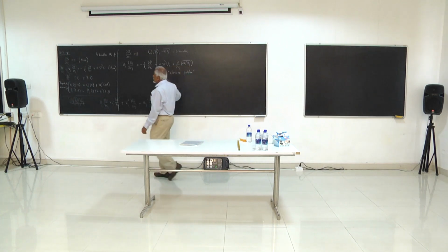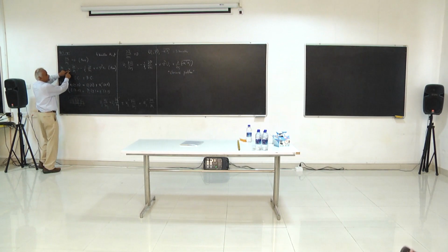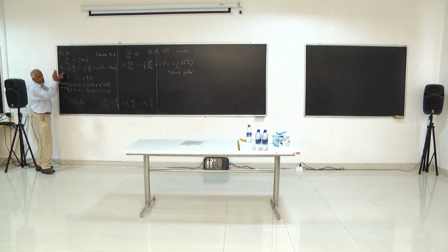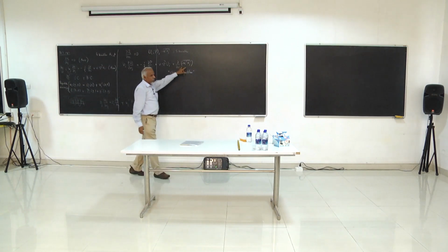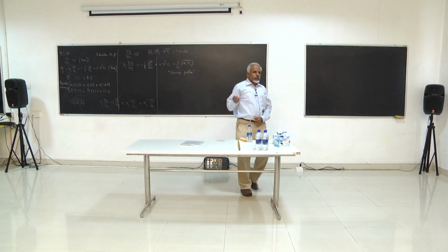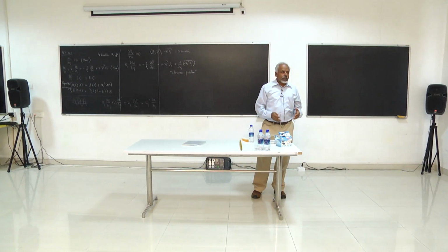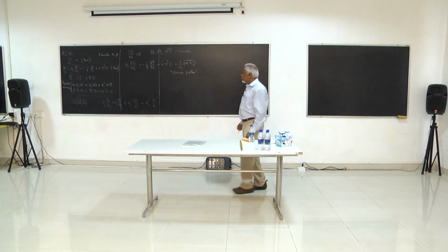But what happens is, because of this nonlinearity, I will have a term ui uj uk. If I write an equation for ui uj, I'll get ui uj uk. And if I write an equation for ui uj uk, I get a term ui uj uk ul, something like that. And this goes on forever, and therefore at any given order, you are not closing the equations.